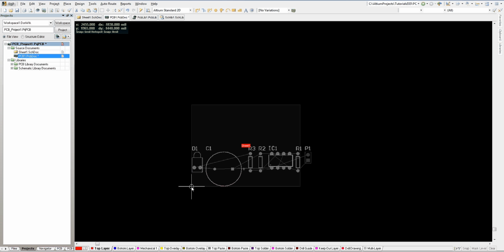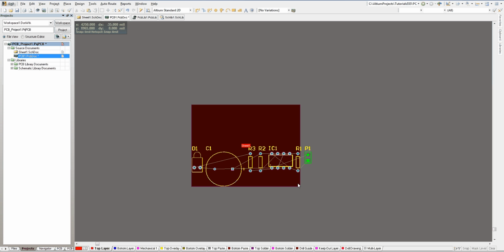As you can see, there's a nice little circle that appears, so you click right there, and you start with a 45-degree mode, which you can toggle with shift and space. So shift space until you get into the 90-degree mode, which makes it much easier for you. Click in the other corner, the third one, and now you can simply press escape, and this should make your board the size that you want.